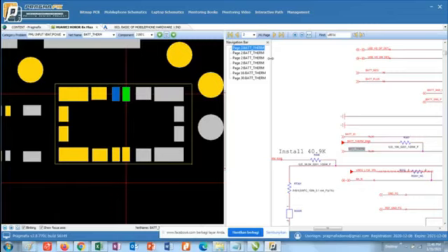And then if the iPhone is too hot, yes, it is too hot. It's related to the battery temperature. The temperature is usually read using an NTC thermistor that is in the battery, but the circuit can be damaged, so the battery is replaced. There's a mobile phone that was healed. Yes, that mobile problem is the thermistor in the battery.